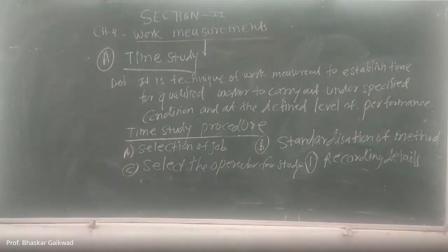Whatever existing things are there, materials, operator, machine, speed, feed, depth, and any other things actually involved in the manufacture, because of which more time will get wasted, such things you have to record. Working conditions also affect this. Then measure the duration of each element.